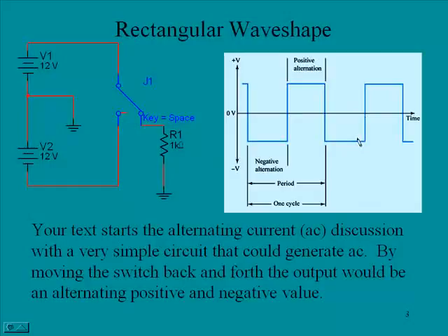So point being that when you have the positive part of an alternating wave, the current is going one direction, and when you have the negative, it is going the opposite direction. So current is constantly changing direction in alternating current, and by its very name, alternating current gives you the sense that current is changing direction. And if we're thinking about 60 cycles household current, that current is changing directions 60 times per second.